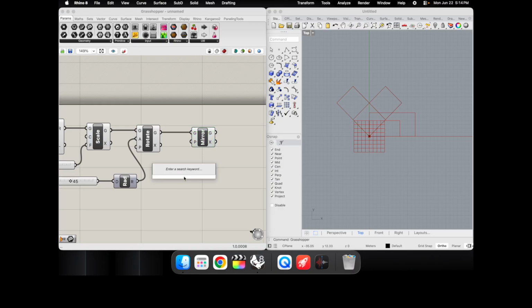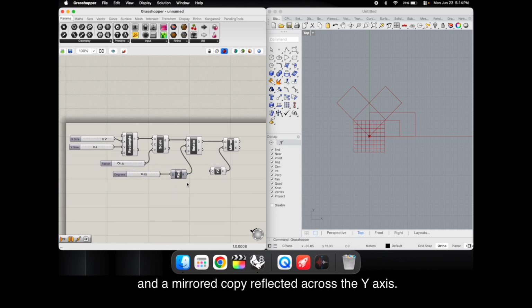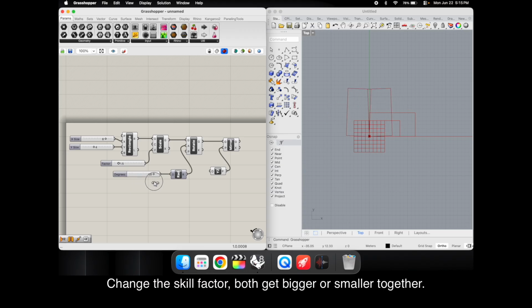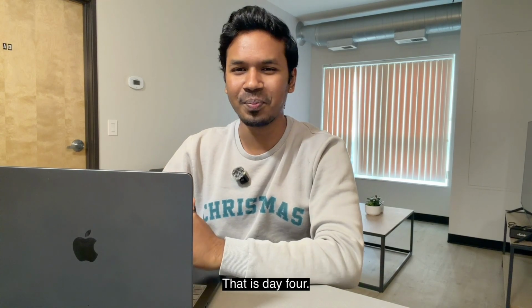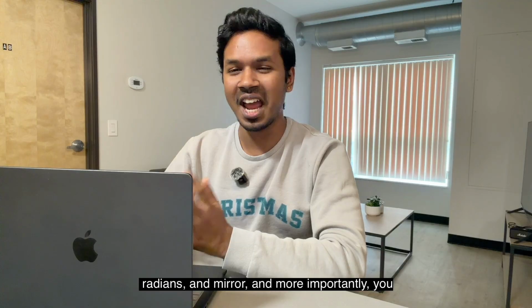Look at Rhino. You should have an original scaled and rotated rectangle and a mirrored copy reflected across the Y-axis. Two shapes perfectly symmetric. Drag the rotation slider. Both rectangles rotate in real time. Change the scale factor. Both get bigger or smaller together. That is a parametric symmetric composition. That is day 4. You now know scale, rotate, degrees to radians, and mirror.